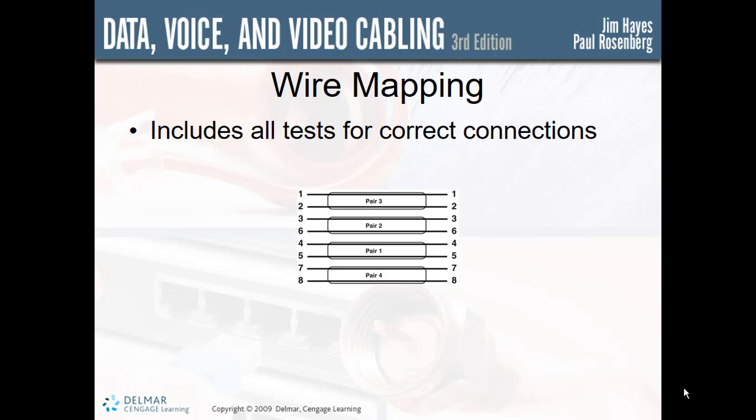As long as the instruments meet the standard requirements and are designed for testing the cabling systems or the network protocols proposed for the cable plant that you're installing, you can expect valid test results and generally accept pass or fail results. Crosstalk, in my experience, has been the most difficult test to pass, especially for Cat5e and Cat6a standards.